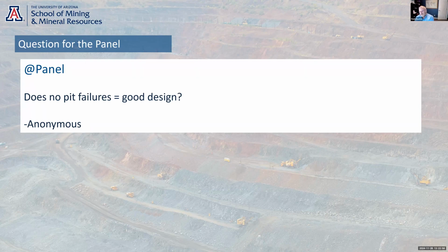Again, I think it depends on the scale, and this is for a large scale failure. Tolerance for global instability, provided you can manage the safety risk aspects, which has to come first. I've seen anywhere from 2 to 5% for a global instability probability of failure. Much more than 5% starts to make the finance guys nervous.